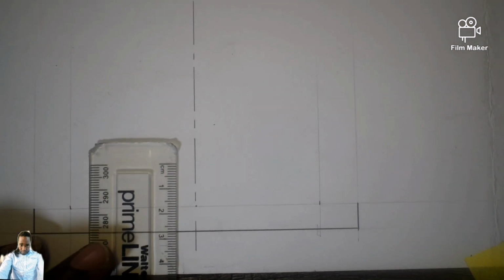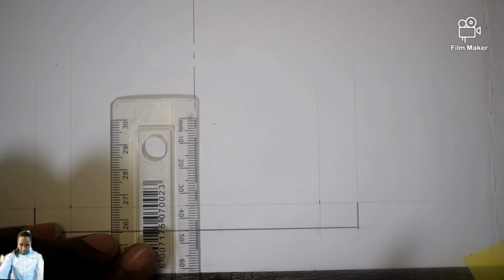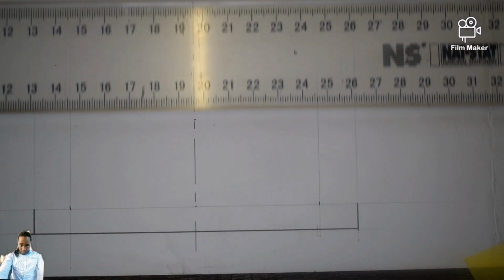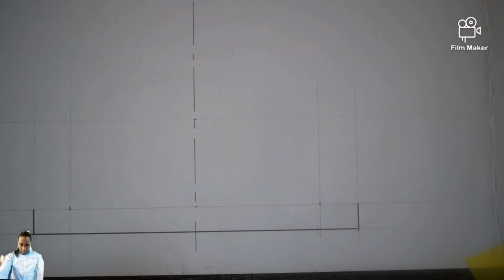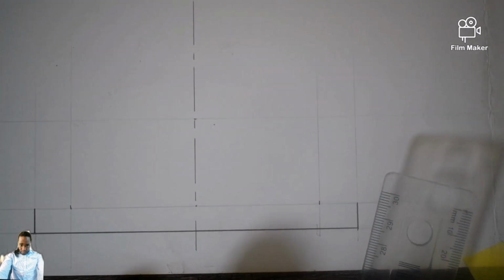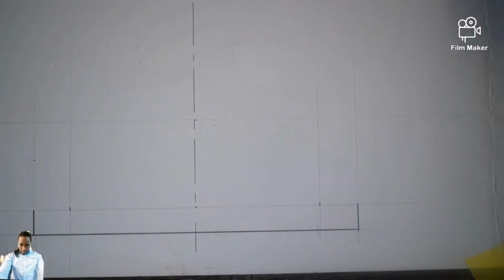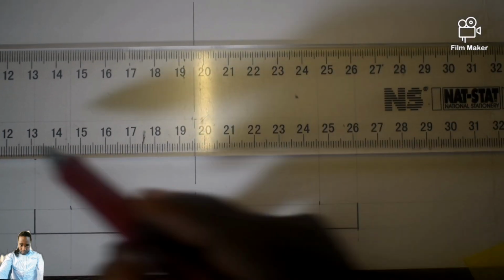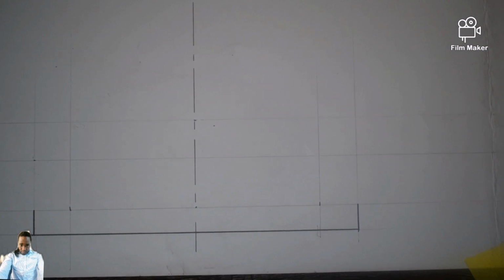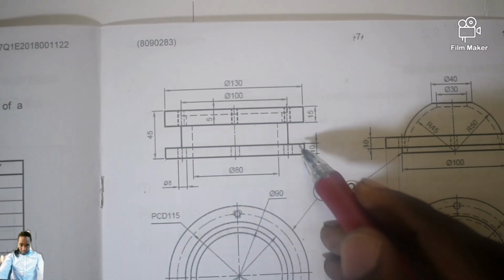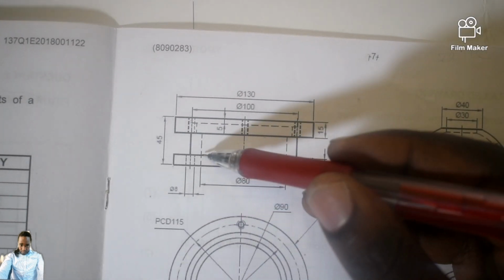So let's do it. From here till there is 45 millimeter. Then I draw a faint horizontal. After I've drawn that faint line, from where my 45 ends, going down is 15 millimeter. So I can do it even here, that's still okay. There's my 15 millimeter. Extend. Now draw a faint horizontal line. So now I can have it dark from here till here, remember we are still in item 1, which is this one. Till there, solid. From here till there, it will disappear.